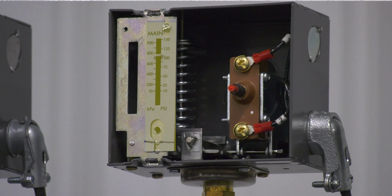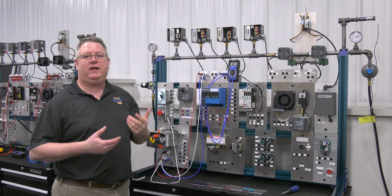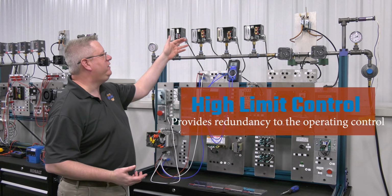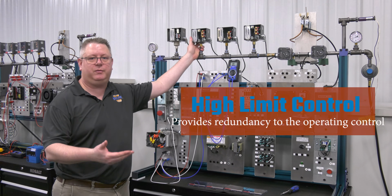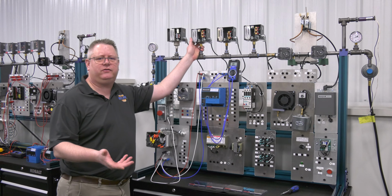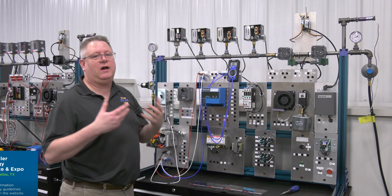And it's got a gauge to set our set point with a screw up top. It has no differential, because what makes this control separate and different from our operating control is that it is a manual reset. So the differential is your finger. The idea of this control is simply to provide redundancy to our operating control, to add a second level of safety on the device. Because if a boiler goes over pressure and fails structurally due to overpressure, that's about as bad as it gets in a boiler accident. So the importance of this is obvious.